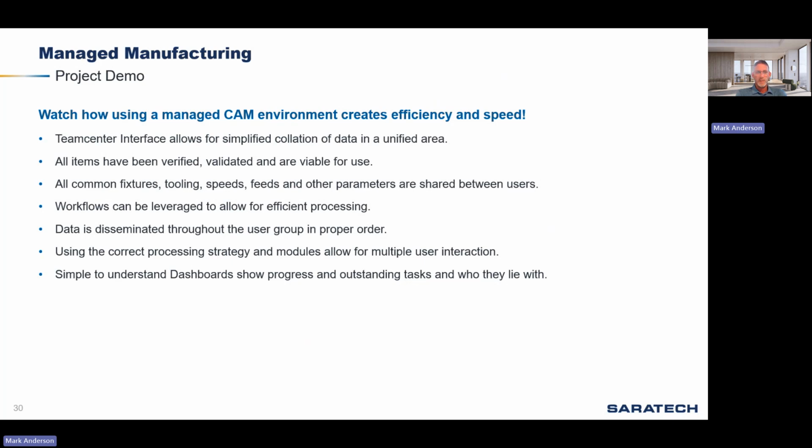that everybody uses. So I'm sure some of you run into the issue of where you do have one vice, but you have to make copies of it, and you copy it into each individual project, because if you do things like move jaw widths open or closed, it blows up pre-existing programs. Your toolpath goes out of date because those jaws physically move in those programs as well. So that's just a matter of training.